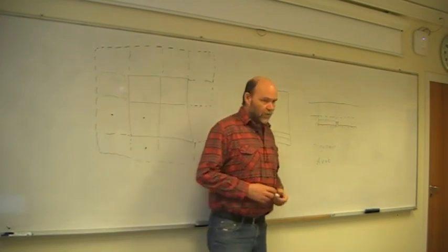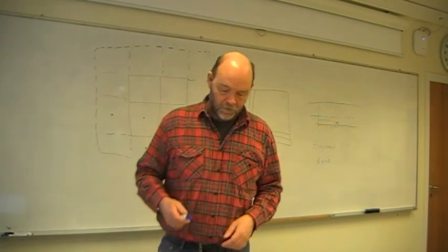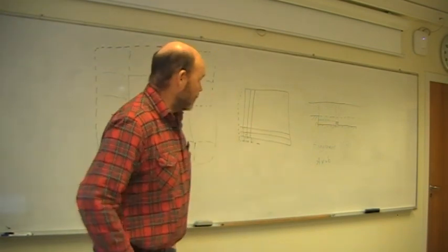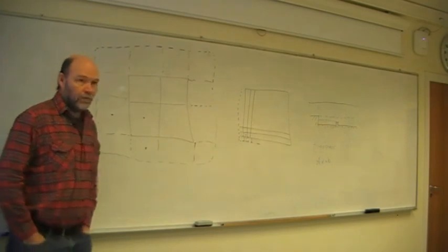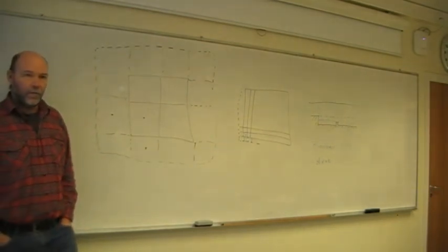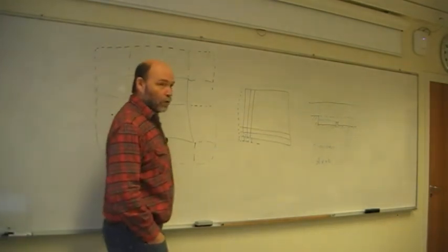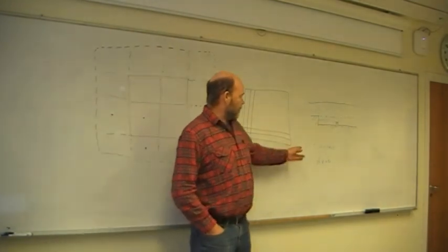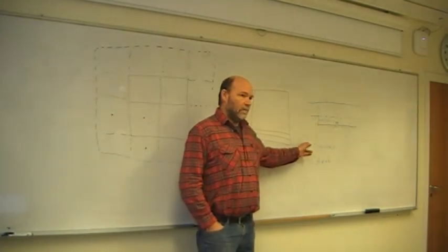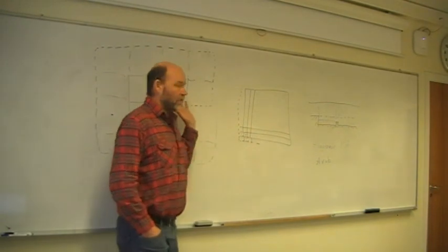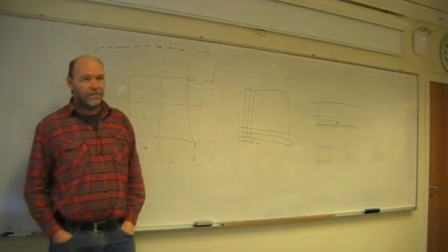I won't go through the theory there, very tedious. But in practice, this means that when you're firing up Fluent, CFX, Star-CCM, any of those, and you choose multigrid, this is the option you get. They don't use it like this. It's not possible in the general case.